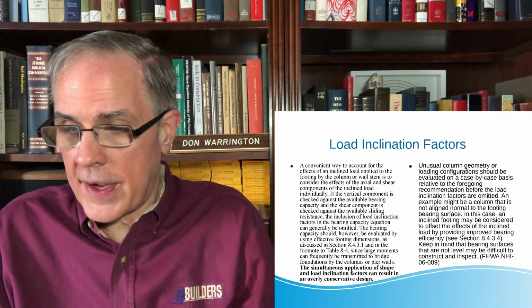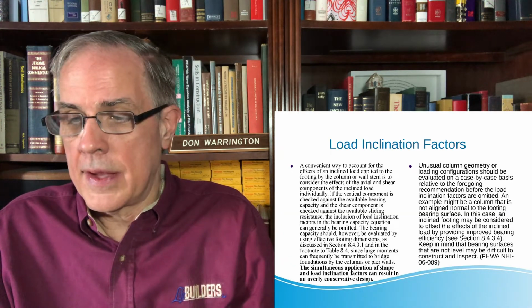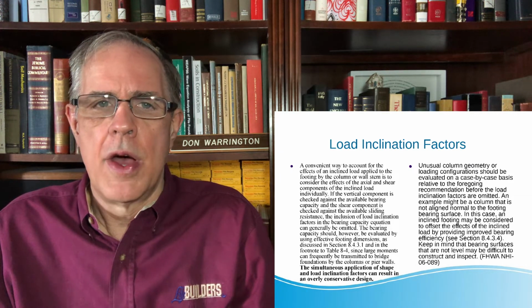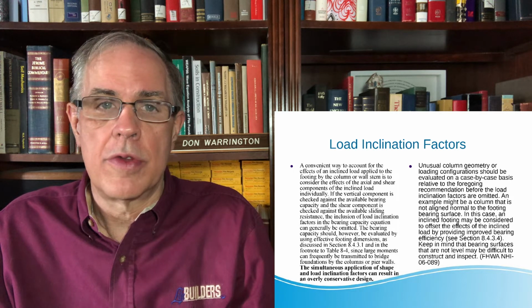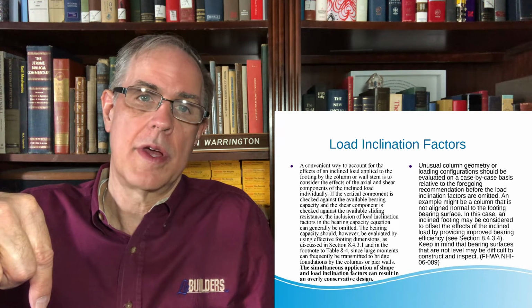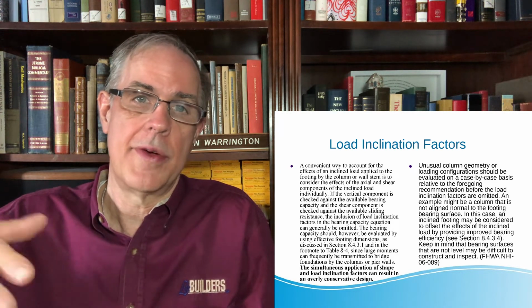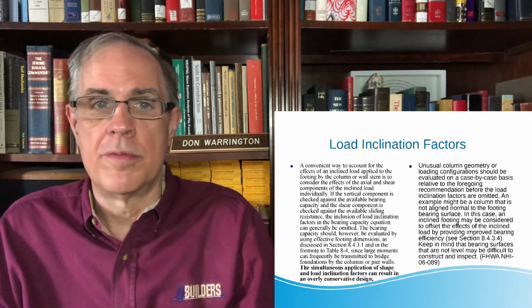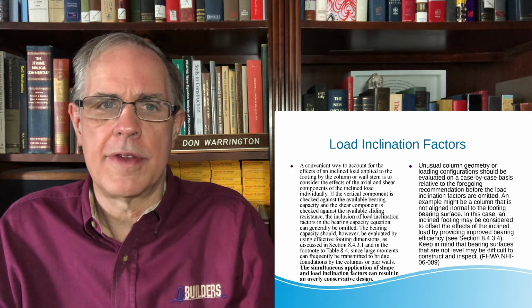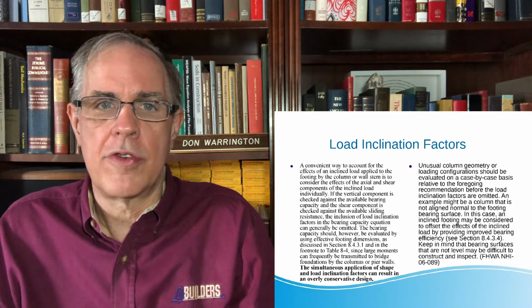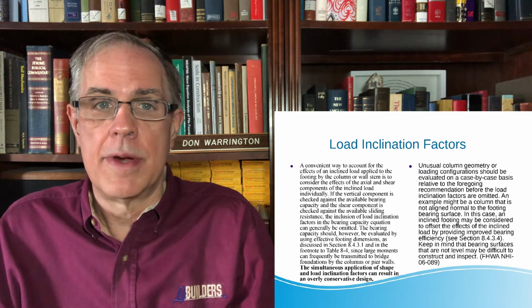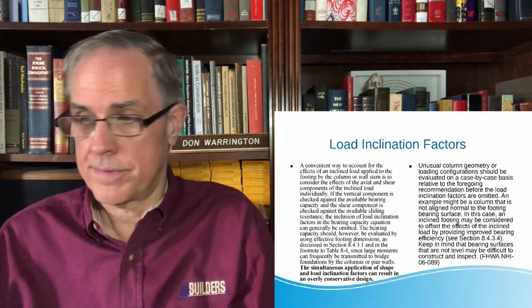Load inclination factors, I do go through a lot of verbiage. There's a lot of different ways of handling this problem, one of which would be to reduce the load on the foundation to its components and treat the vertical component just like you would any other load, and the horizontal component like a frictional load. There are a number of ways of doing this. I don't spend a lot of time emphasizing the issue of load inclination factors. You do get into that to some degree when we get to retaining walls, but we just split up into components.